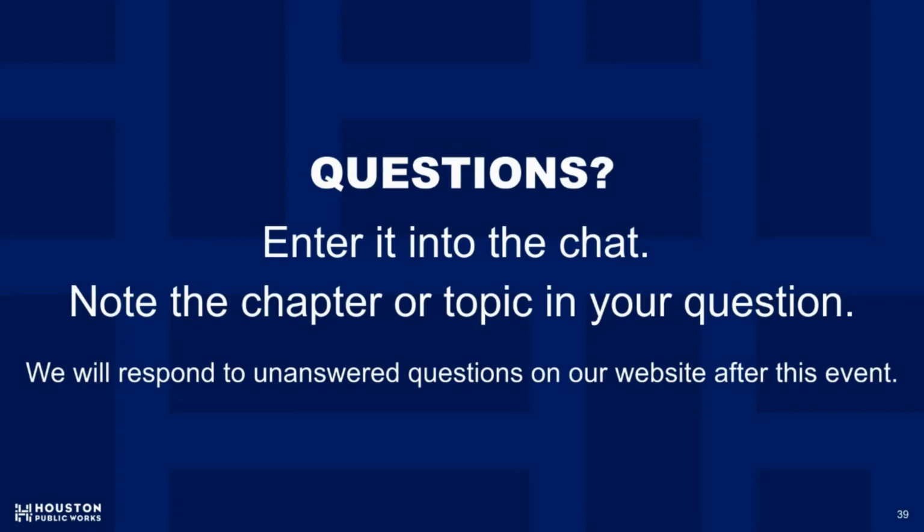Thank you. What is required to be provided on a subsurface utility exploration level A report? A precise horizontal and vertical location of utilities obtained by actual exposure is required. A brief explanation of level A of subsurface utility exploration is provided as mentioned in chapter 6. Also, subsurface utility exploration deliverable requirements for telecommunication facility can be found in chapter 16.